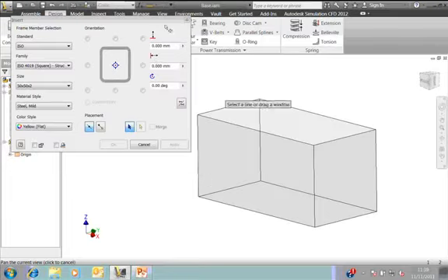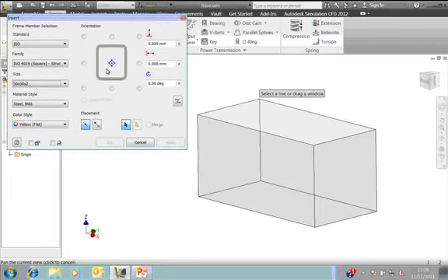Okay, now for the box section, I'm going to use the centre to align with all the edges on the skeleton. I'll do that very quickly, but just as a tip really, if you're adding other sections, C-sections, beams and so on, then select the one edge first and place the section, and then get the alignment right by clicking on the relevant buttons here to align it correctly. And then always move off from one end to a line that connects to the edge that you just selected, and just move around and select individually to lines that are linked to the beam that you've just selected. The way that works then is it uses the alignment of the first edge to sort out the alignment on the second and third edges that you select.